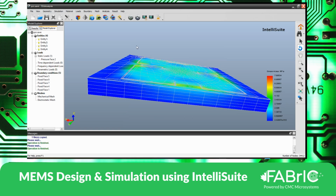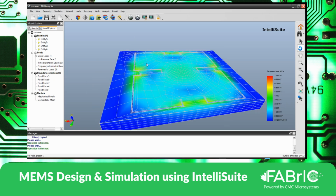So now the piezoresistive based MEMS pressure sensor has two types of physics now, two types of simulation. One is mechanical based simulation, another is electrical based simulation, because the output that comes out of these resistors will always be a potential. So this piezoresistive pressure sensor works on the principle of Wheatstone network.